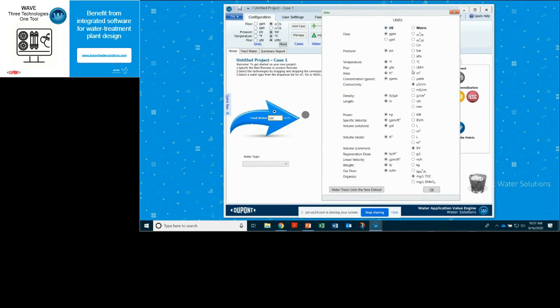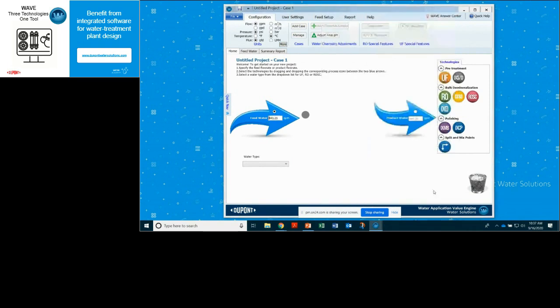Often a design request will come in as a simple SAC SBA, but people are open to optimizing around that to see what the best configuration may be, maybe adding in a WBA or just looking at the strong base anion itself. So Garth, can you run an example for us?